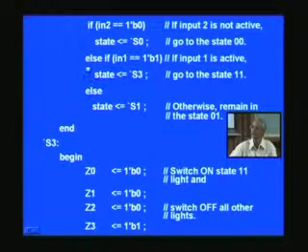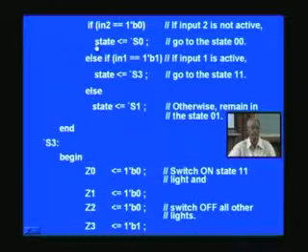Please note that at this point when it enters, it implies that in2 is 1. If in2 is satisfied, this will be satisfied, and it will exit this block. It won't come to this. So that's what I was saying, if else if have this vetoing power, that is, a priority can be assigned in this way. So if the top priority is met, it merely exits the always statement.